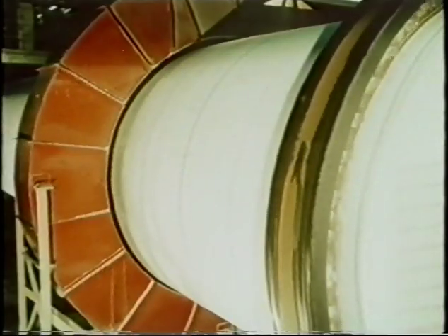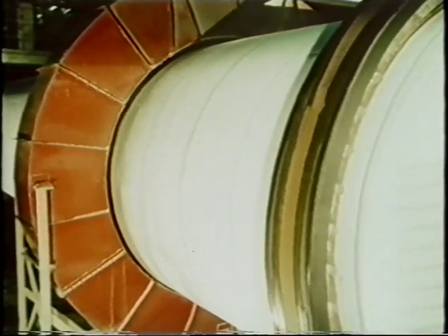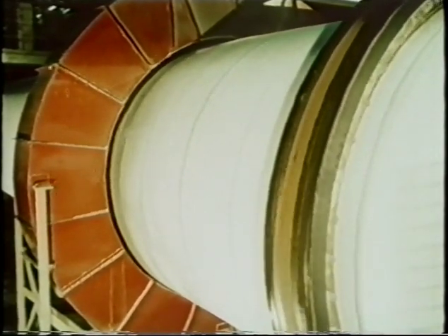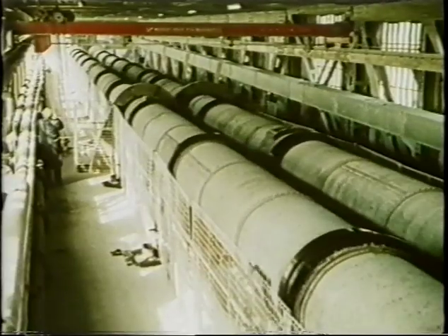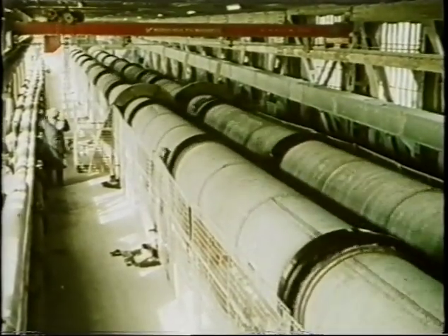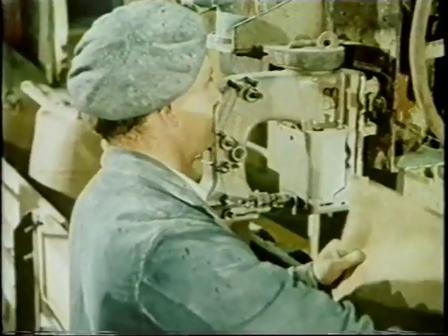Onto the vacuum filters, large rotating drums covered with blankets. The ammonium chloride solution is sucked through continuously, while the bicarbonate crystals left on the outside are scraped off. They pass on to the calciners. Here the bicarbonate is converted to normal carbonate. The hot sodium carbonate passes along long cooling conveyors to the silos and packing sheds.